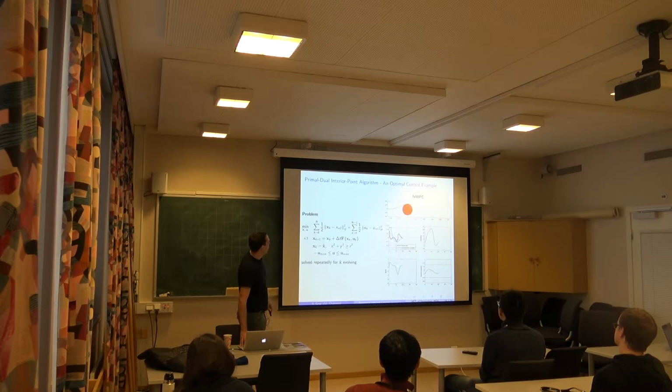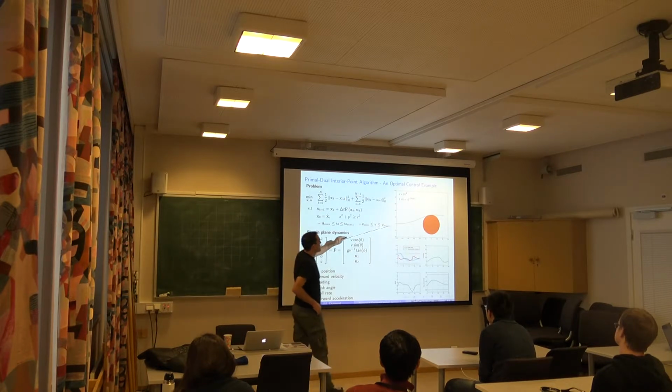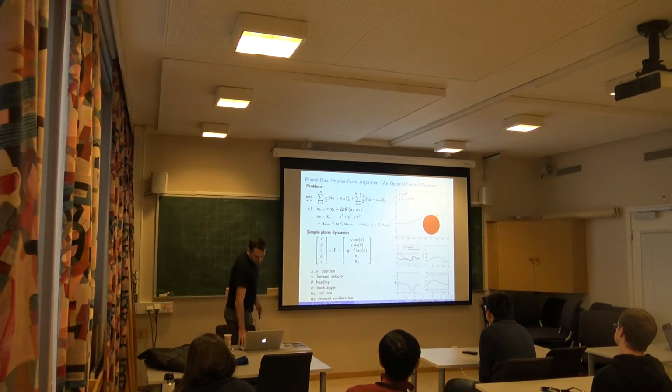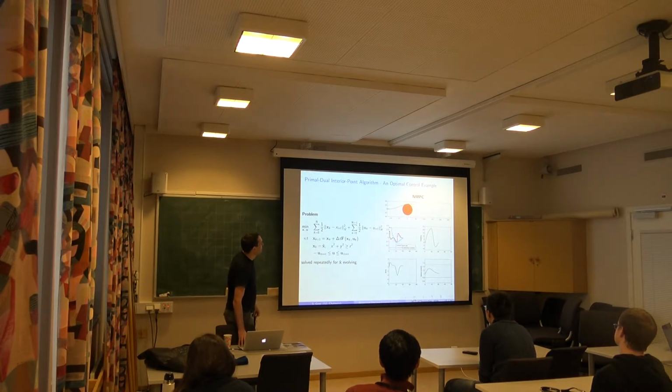Right? And then we can go MPC style on this, which means you compute this trajectory, the plane will be here, initial conditions, and then you just apply the first control move, so the controls would be here. And after one sampling time, you would recompute everything based on the latest state estimation. And then you would have an effect like this. Right. So that's typically the kind of thing you may want to do in your projects, like doing some MPC-like things on a control problem. Okay with that? Yeah.